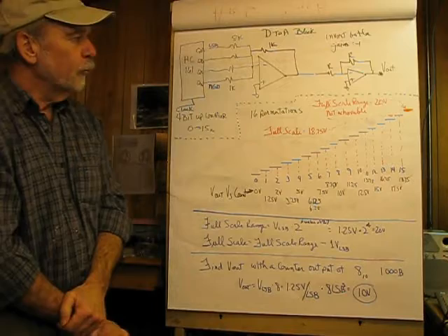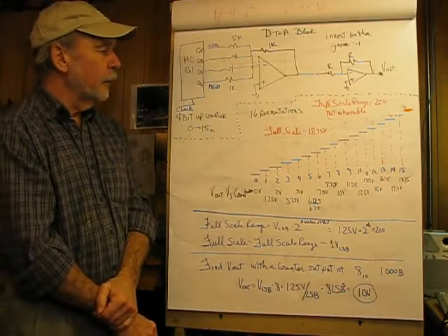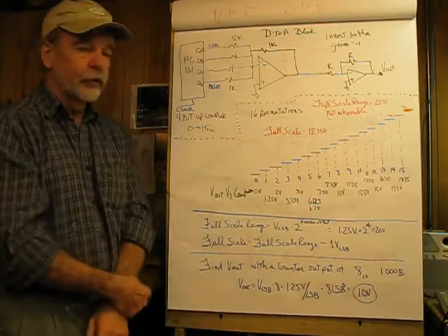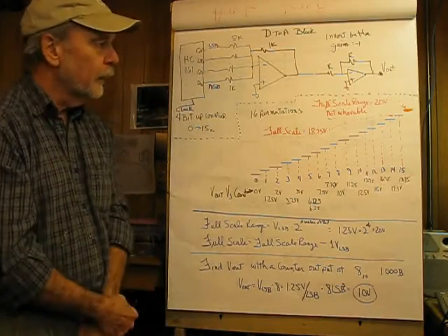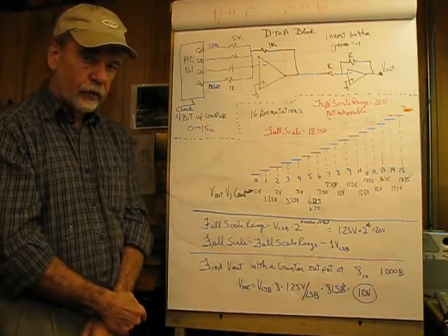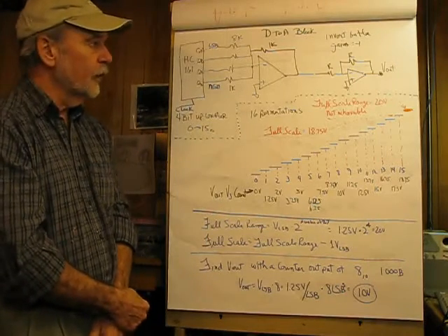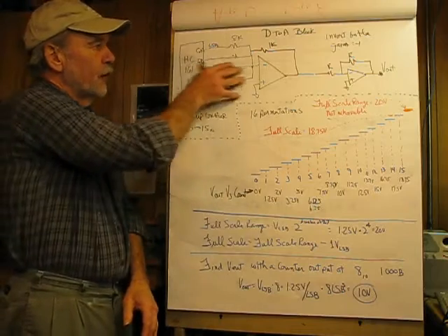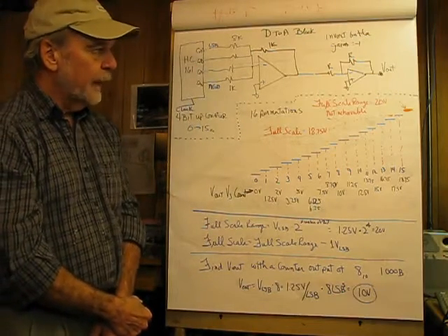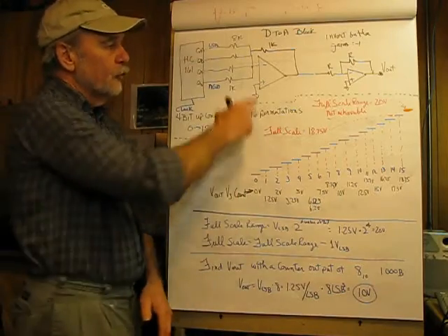So let's take our little binary weighting here and drive this by a 4-bit binary up counter. I'm using an HC161 here, and it's going to count from 0 to 15, so there's 16 permutations in this, and we're just going to let this feed our input here, and we'll take a look and see what happens. So same circuit as before.